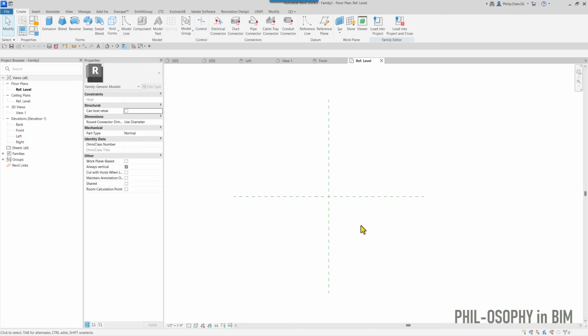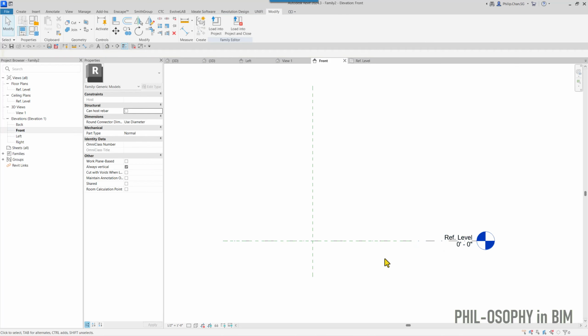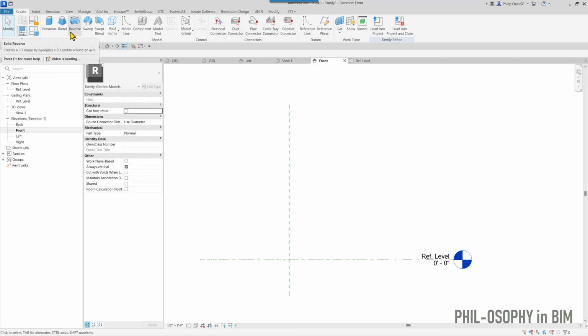This is a little bit newer technique that can utilize a revolve, which is a revolution geometry, to achieve the rotation setup. Okay, in this case, if I want to mimic the door panel rotation, I first have to create a geometry in my elevation. So I'm going to go to the front elevation here. I'm going to pull this a little bit over. So I have to basically create a revolve here.